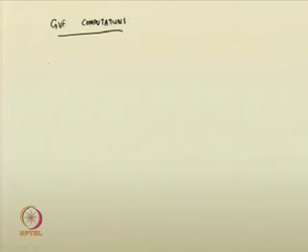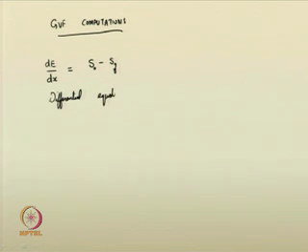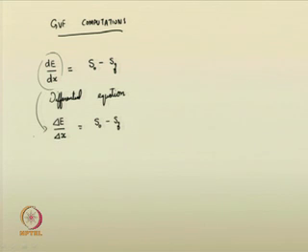you can see that we had derived or suggested that the slope of the energy equation is S0 minus SF. Then this is a differential equation. Now, this differential equation, the derivative is substituted by an algebraic expression, del E by del x is equal to S0 minus SF, like this we suggested. So, here this derivative is being approximated by the algebraic expression. From this, you subsequently obtained the direct step method for computing gradually varied flow profile, del x is equal to del E by S0 minus SF.